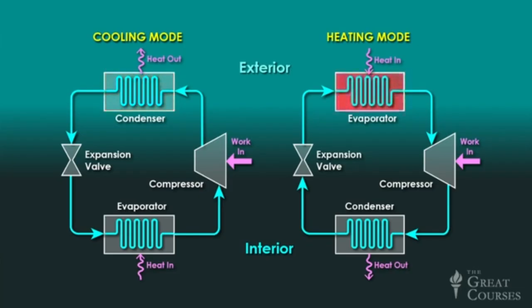Conversely, in the heating mode, the coil transfers heat from the surrounding environment into the refrigerant, causing the refrigerant to boil. Here, raising the temperature of the surrounding environment also enhances the efficiency of the process, while also eliminating the principal limitation of air source heat pumps, their sharp decline in heating performance when the outside air temperature drops below freezing.